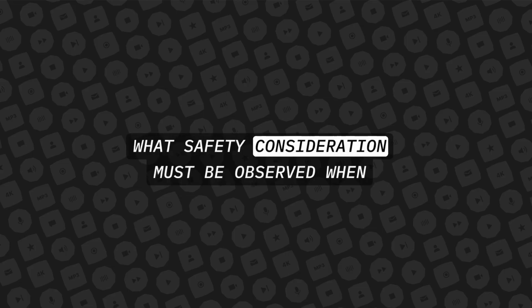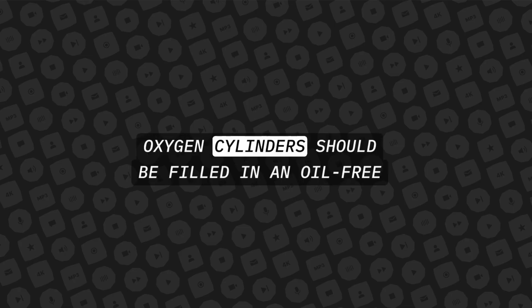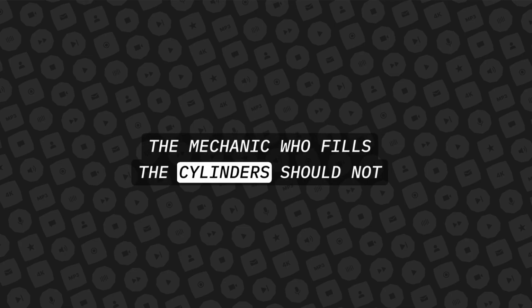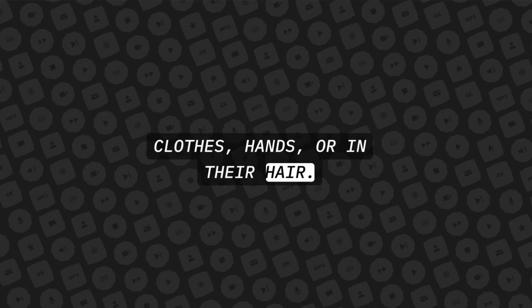What safety consideration must be observed when filling oxygen cylinders? Oxygen cylinders should be filled in an oil-free environment. The mechanic who fills the cylinders should not have any petroleum products on their clothes, hands, or in their hair.